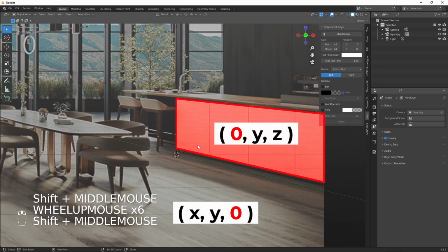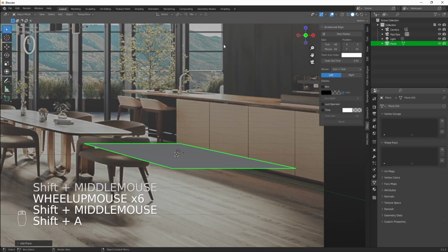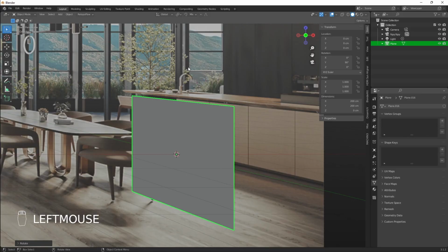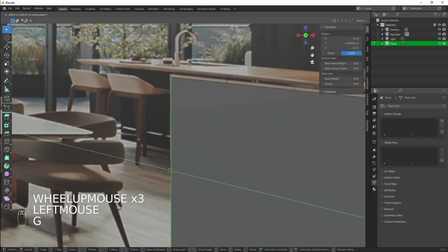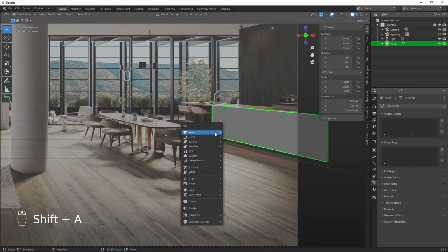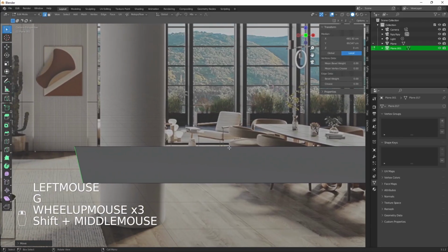And because we know one of their coordinates, we can safely align their meshes with the image and get the correct results. So I can add a plane, make sure it has its x coordinate set to 0, and now align its edges with the image. And then add another plane for the floor, ensuring its z position is 0, and also do the same thing.